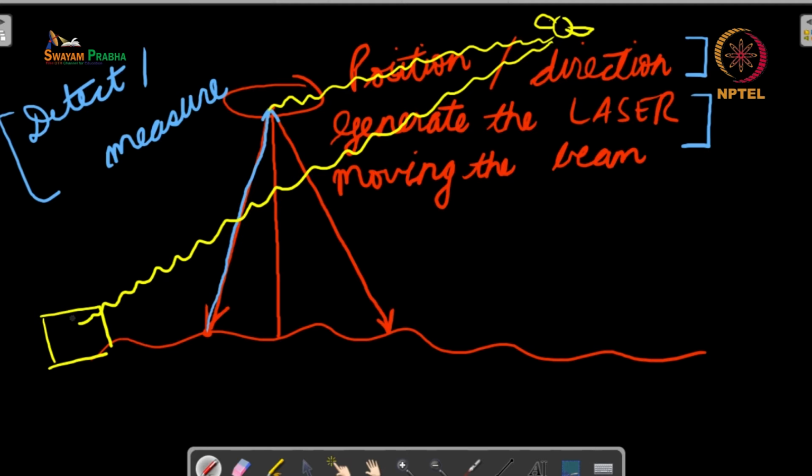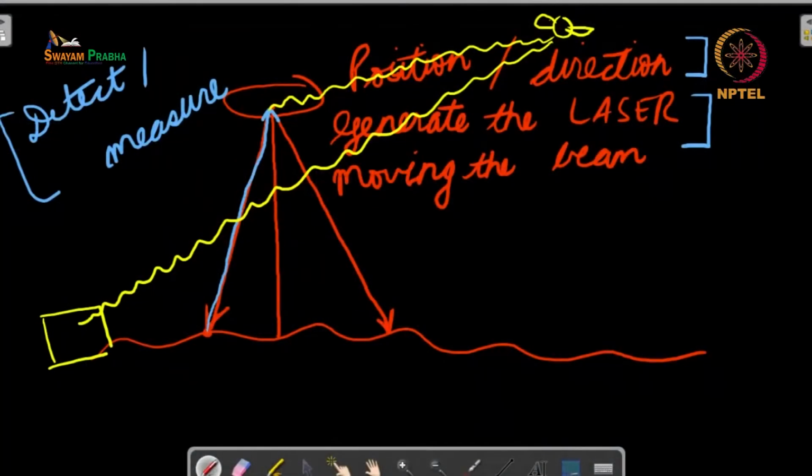Now it is possible that the signals that the satellite is sending get certain amounts of errors in generation, or errors that occur during transmission, especially the errors that creep in because these signals are moving through the atmosphere. Once that happens, we will have certain errors in measurement. Now differential GPS tries to eliminate that error by doing a subtraction.